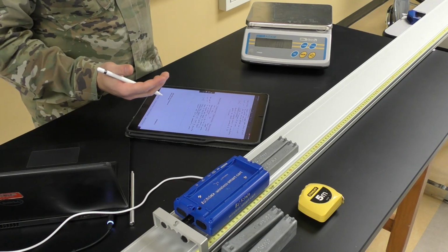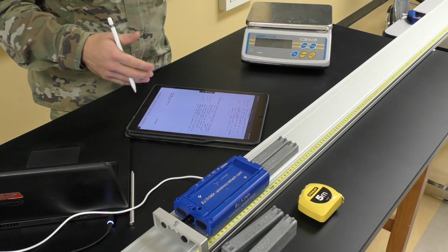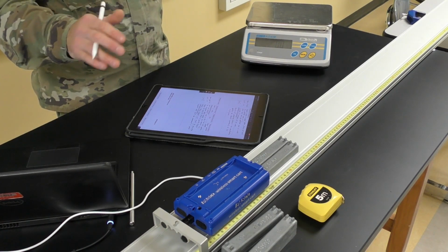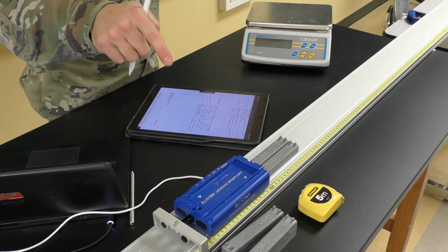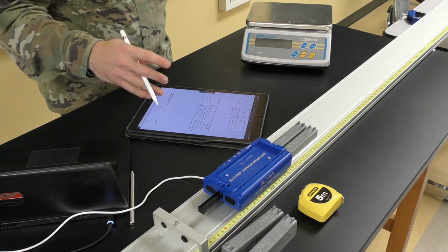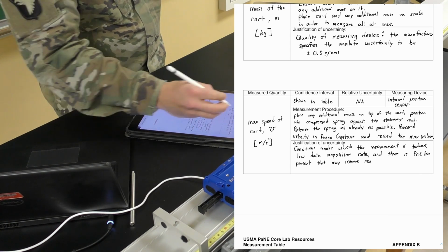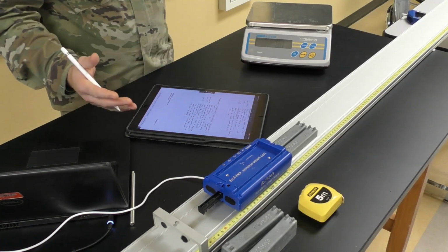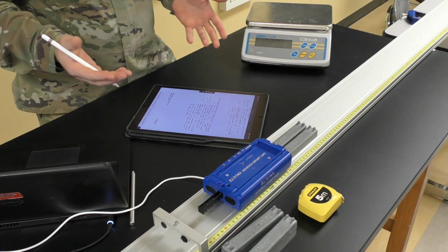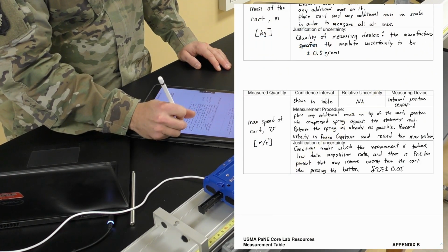So by the conditions under which the measurement is being taken, because I'm using a low data recording rate, I think that it's possible that I miss the maximum speed. And then also because as I press this button, I may absorb some of the energy through friction, either using my finger or the metal rod. So for these reasons, I took a number of measurements. I found that they kept on consistently going within a window of about plus or minus 0.05 meters per second.